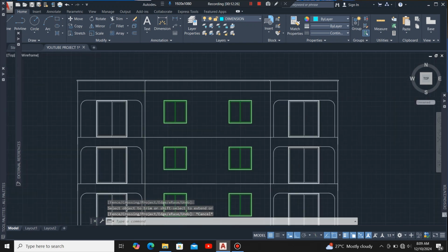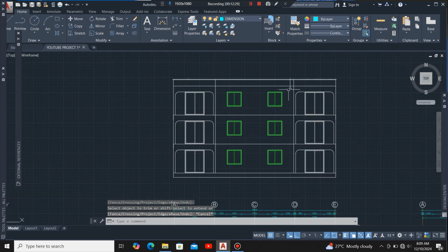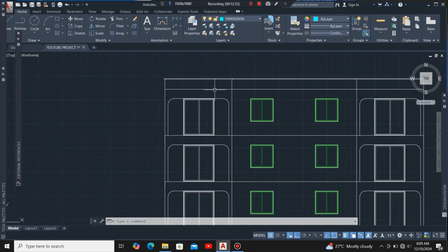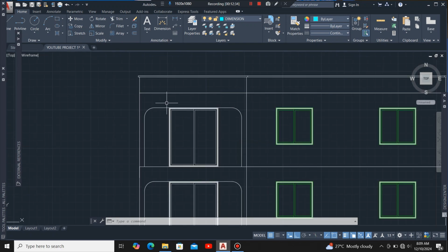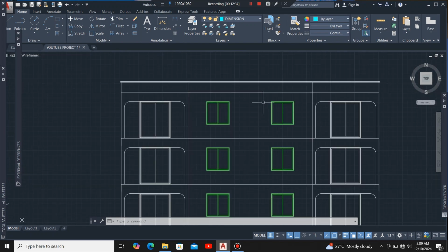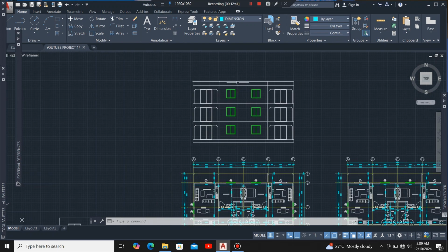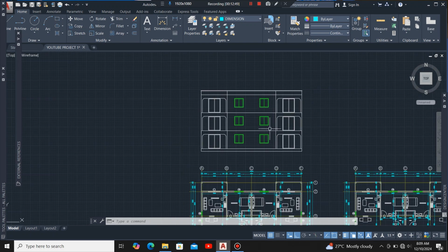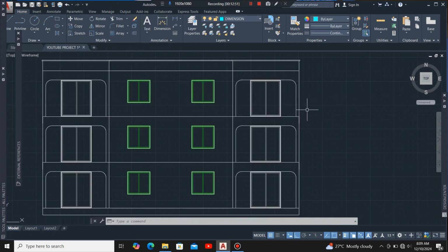Okay, so you can see that I've just created a simple parapet wall just above the last floor. So it's going to be a flat roof, a solid slab on top. So next I'm going to put the guardrails on these different levels. But we just need to create them and not yet model any.